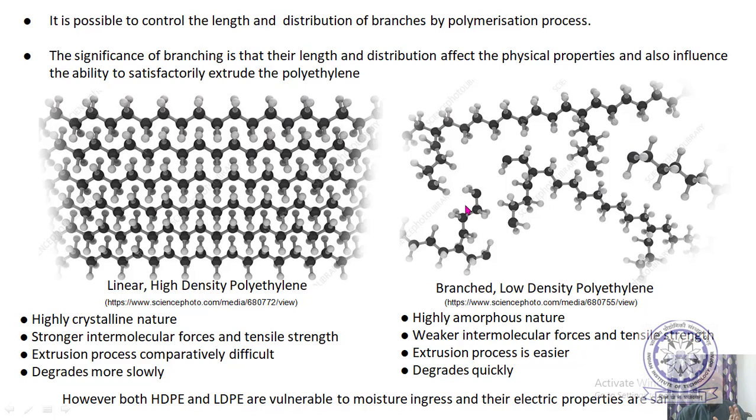What is done is that it is heated and melted. The molten polyethylene is laid on the cable in a mechanical structure known as an extruder. Through this extruder the central conductor is continuously pulled out, and while it is coming out, the insulation is laid on the conductor uniformly, and the cable appears in a cylindrical fashion. This process is known as the extrusion process.